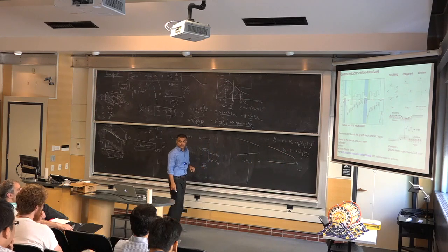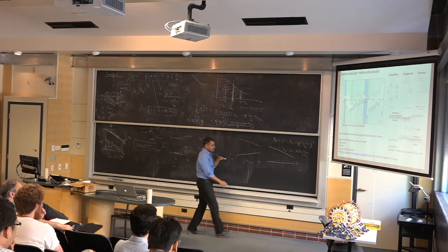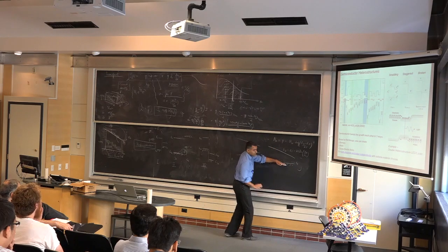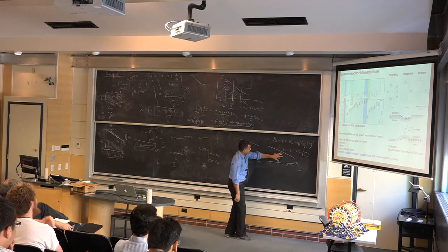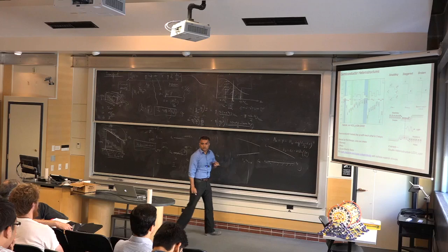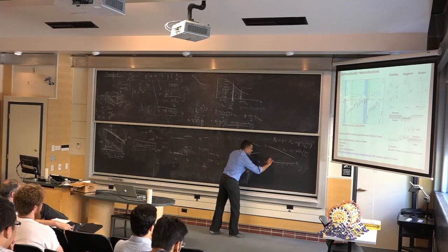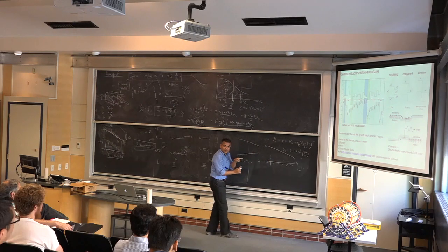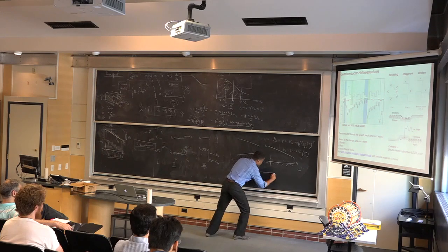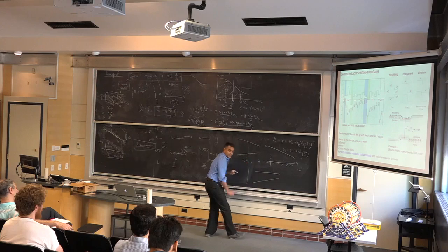Make sense? So by doping, that's how you control how the band diagram really looks. You dope it p-type, this is what happens: the band diagram will look with conduction band here, valence band here. By doping, you fixed this. And you dope it n-type, as you can see, you'll switch it around. The conduction band will become flat, but the valence band will look like that.